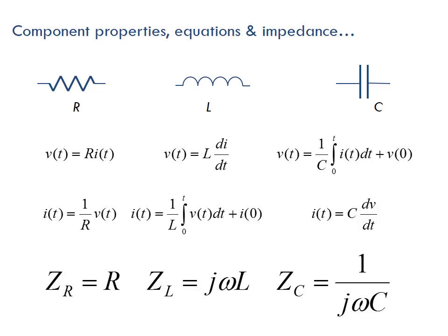And we'll get to capacitors in a second. But if you look at our impedance for inductors down below, it's j omega L. So you have the inductance value, you have omega, and you have j. Essentially, it's a function of the specific signal going through. So you do need a sinusoidal signal to make an inductor work.